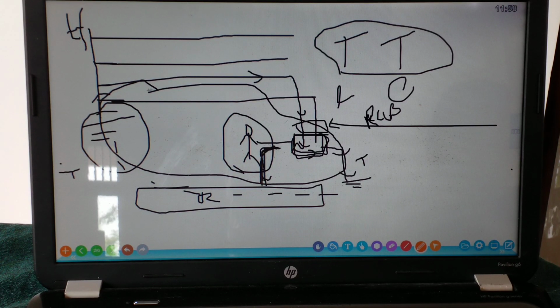In the fault loop path, you can see the earth is also engaged. The resistance of the fault loop path, the loop impedance, may always be a little high, because earth resistance is also there, rod resistance is there, and conductor resistance is there.